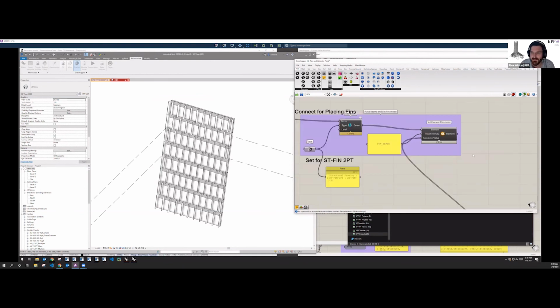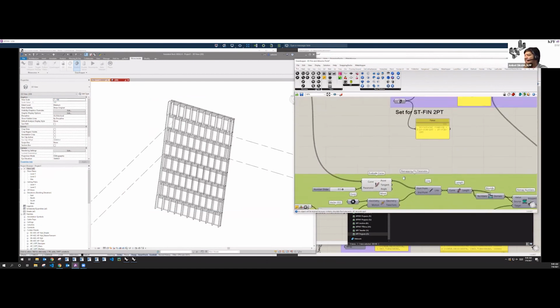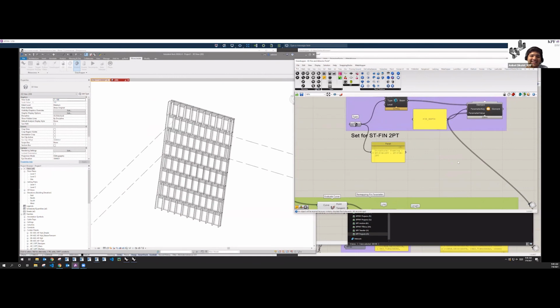So, like anything with Grasshopper, or Revit, or any program really, save often, freeze things you don't need to be computed at the time, and then unfreeze them when you do want it to run again. With Rhino.Inside, you're seeing the geometry inside Rhino as well. So you can freeze the creation of the Revit geometry, play around with your parameters, and then just create the Revit geometry after. It'll be a lot faster. That is good logic. Yeah.